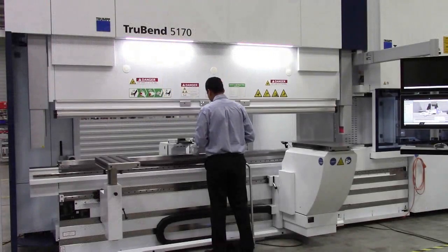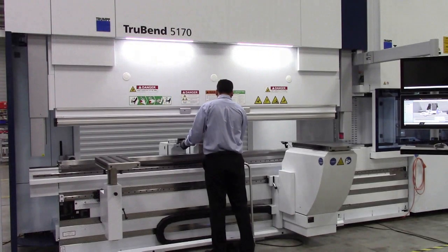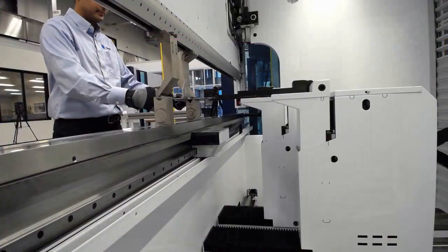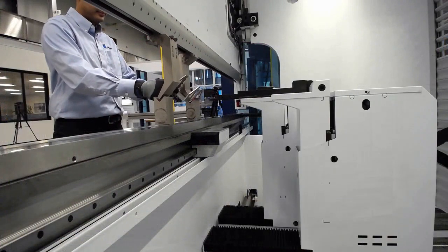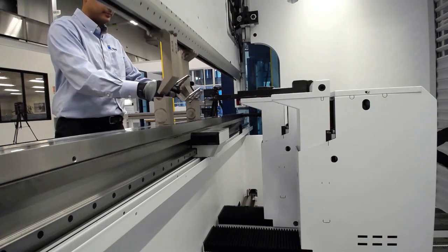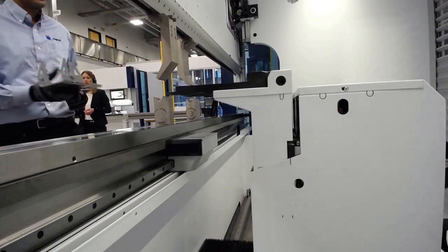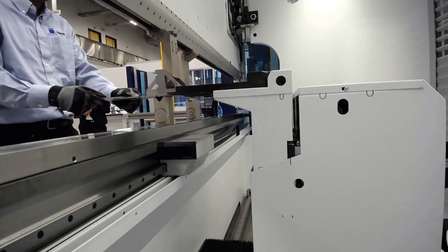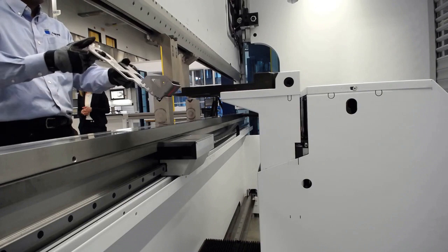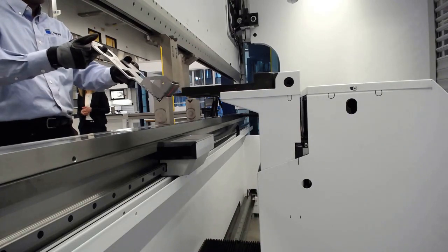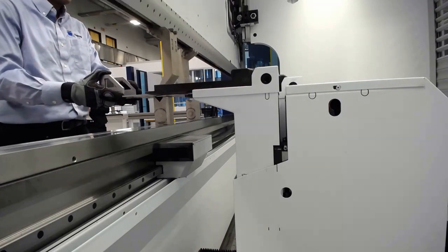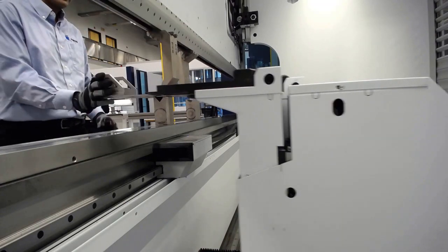So with the ACB laser, it's about 1 extra second that it takes for the measurement, but then we make sure that the angle is really perfect. So it will hit it twice. So first to test the spring back, and then to bring the part to the actual angle that we are requiring, or that we programmed. We can see here our 6-axis back gauge in the back.